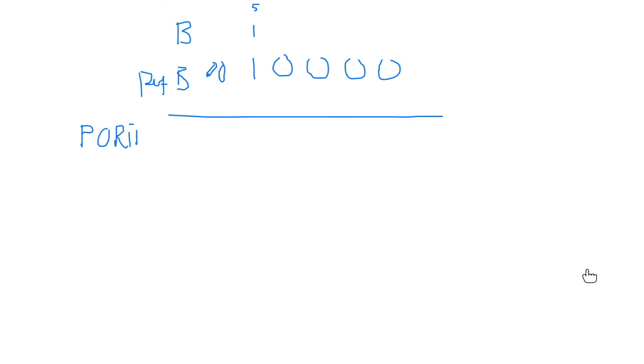If we write to the whole of port D, if this is a 1, because we did an OR, it's still going to end up a 1. We don't care about that. We don't care about these. We don't care about that, because we are doing an OR. It wouldn't change it. But the bits that we are interested in will be forced to a 1.